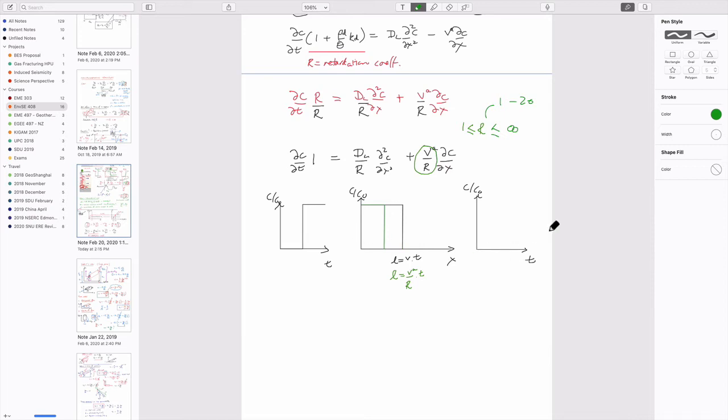And so if we look at the residence time distribution, this isn't absolutely correct, but before we could write time as being equal to length over velocity, right? Length is meters and velocity is meters per second, so by definition that's time, just from the units.